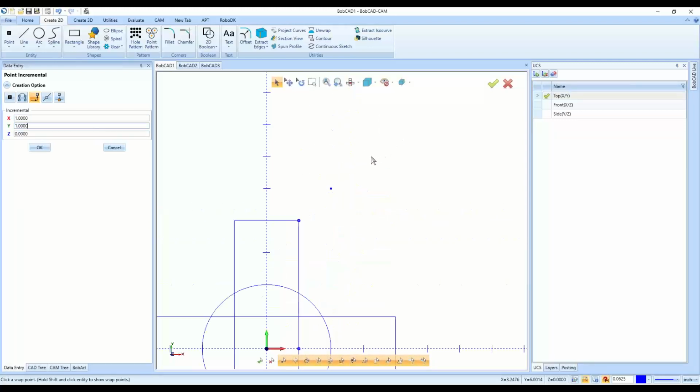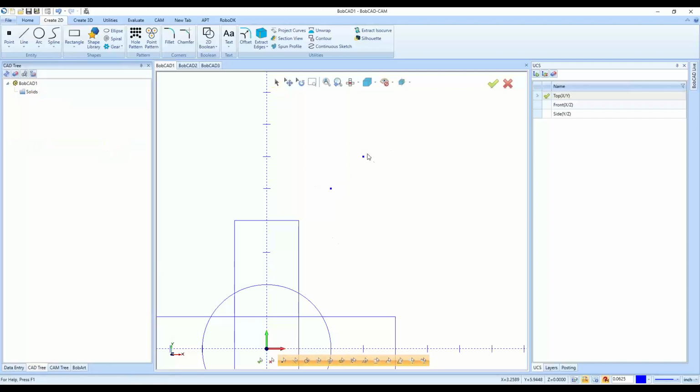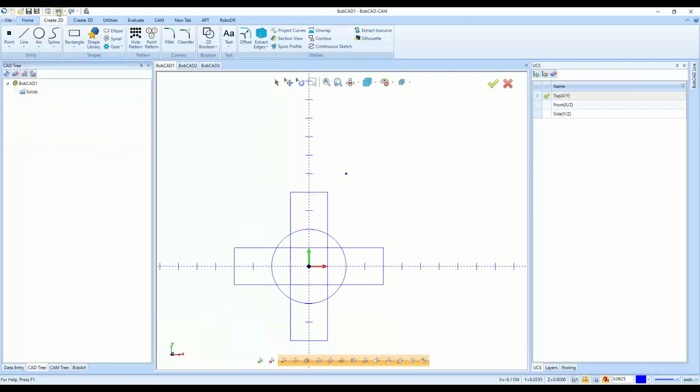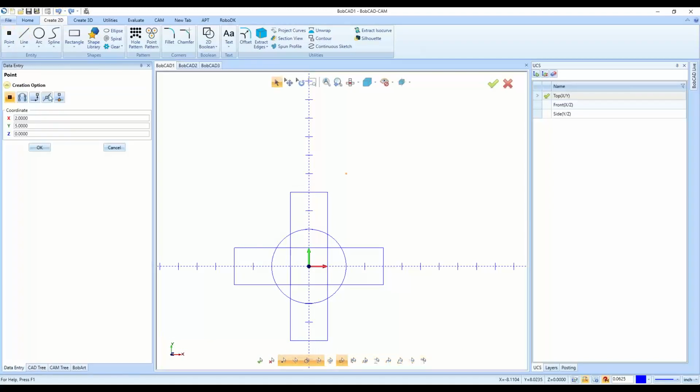And then I can incrementally do that. If I highlight over that point, it'll move over and create those 2 points for us. But anywhere along those lines, say 2 inches, 4 inches, and start at a point, it'll move 2 inches in X, up 2 inches in Y to create a point.